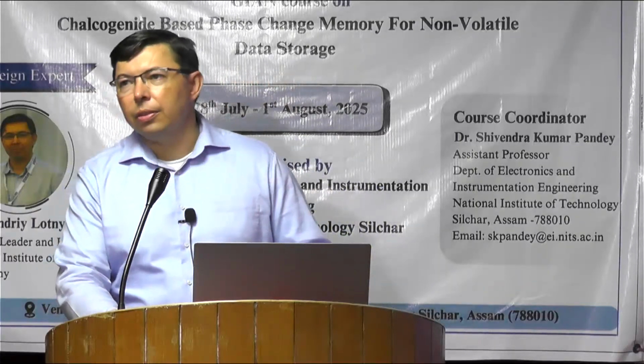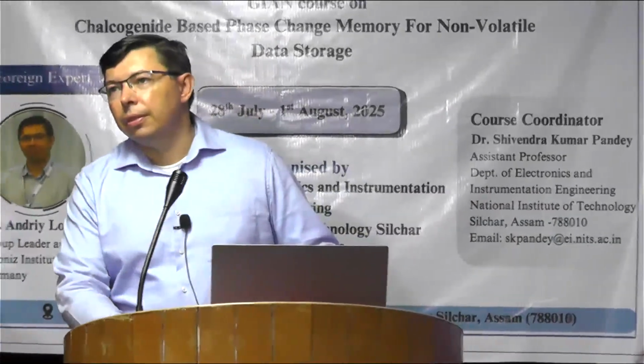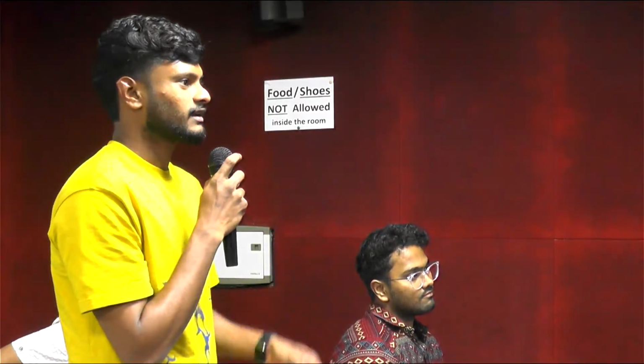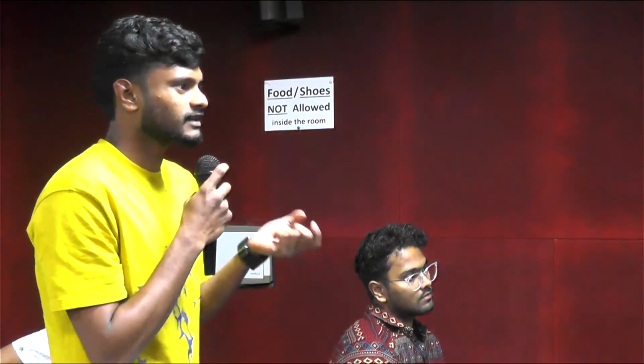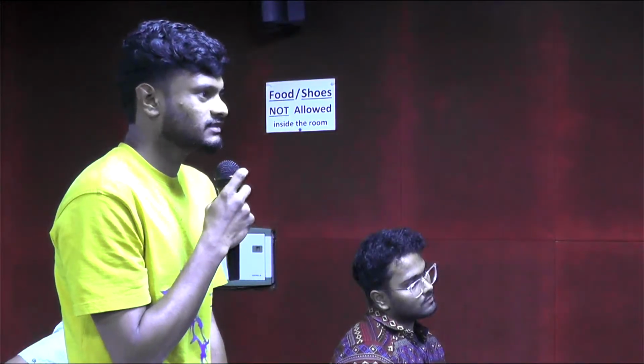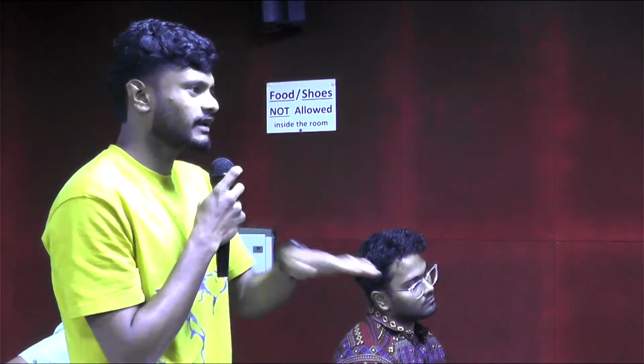Data retention capacity is decreasing for amorphous while we are exposed to air. I'm also getting the same thing, very low data retention for the amorphous phase. So what is happening there actually? I was curious: you are saying the data retention property of the amorphous phase decreases while exposed to air? Yes, the data retention property of the amorphous phase is decreasing while the oxide layer is formed.